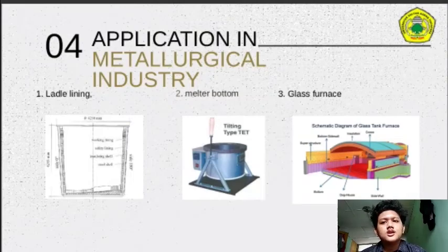And the last is the wall and the bottom of the glass furnace in contact with the molten glass, which are currently generally built with zirconium containing refractory bricks. Also, zirconia bricks are suitable for special regions of the glass tank such as the paving part and secondary layer of paving, bottom, backlining, flowing spout, and spinning portion.